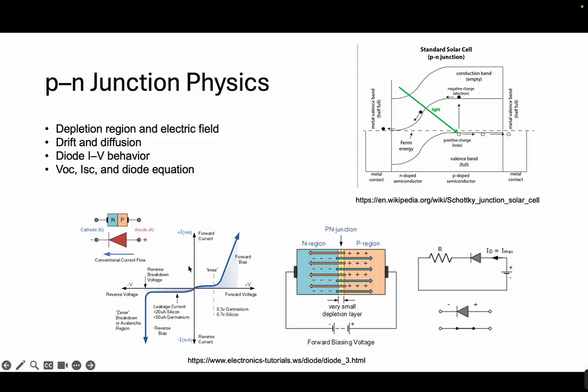So as you can see here, this is an IV curve for the diode. By increasing the forward voltage, you go higher, and then you have an exponential term, and if you make the voltage negative, you then have a breakdown or avalanche region.